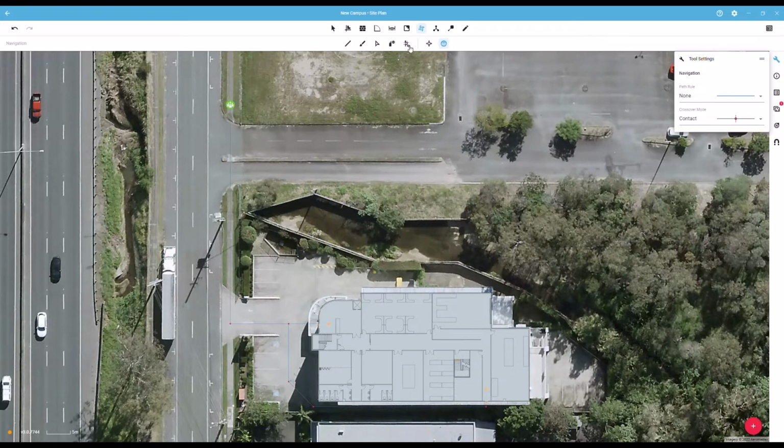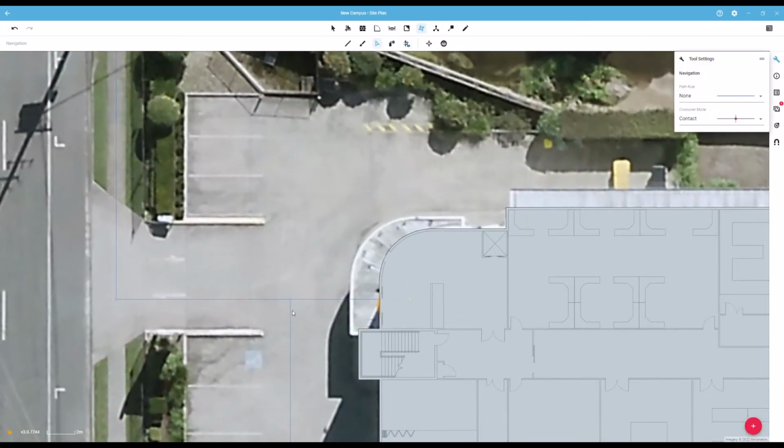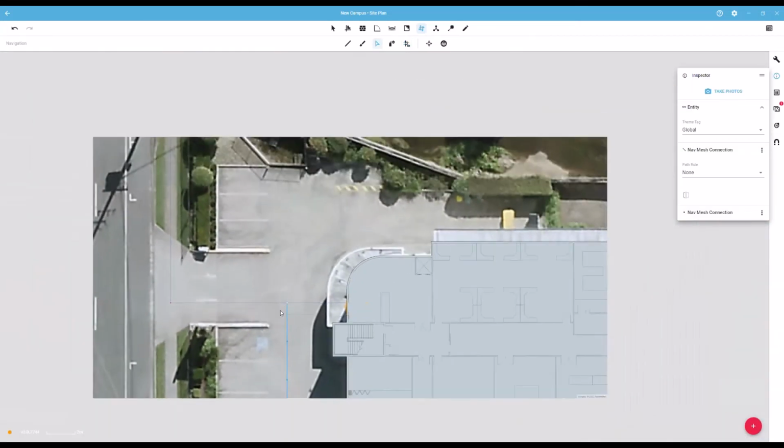You can then use the path preview mode to check that all of your evacuation paths work and that there are no gaps in the lines. Start at the assembly area and click and drag your cursor back to preview each path. You can also click inside of a building footprint to see all of the paths available for that footprint at once. If any paths are not working, check that the corners and joins are all correctly snapped together.